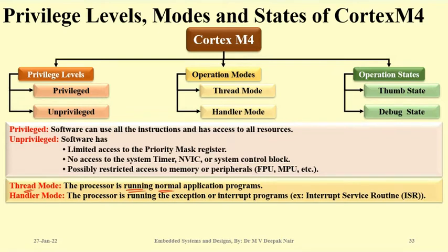But whenever there is an interrupt or any exception, meaning an error mostly, or interrupts with very high priority, those are called exceptions. And at that time the system gets into handler mode. It does not mean the computer or the microcontroller do not have any control over the system. No, it still has the control, but it has entered into an error based scenario. So you will have to restart it, reset it. Might be possible the things will get okay, otherwise you will have to check which error is occurring and how to fix that error. So that is called handler mode.